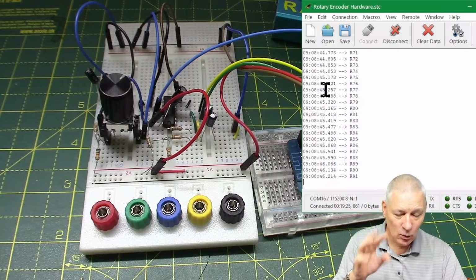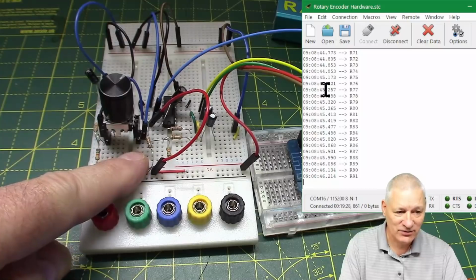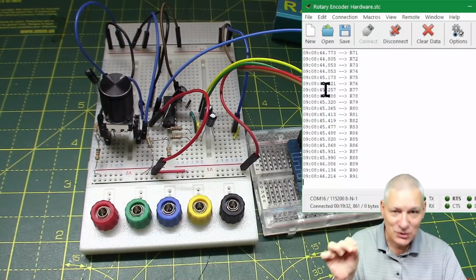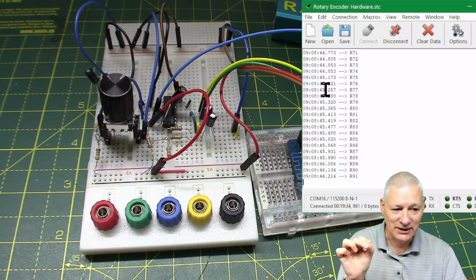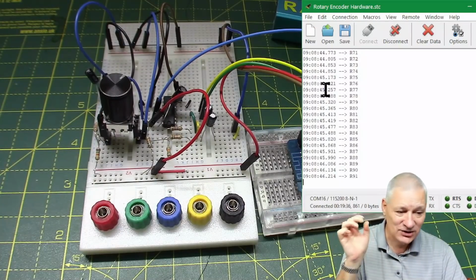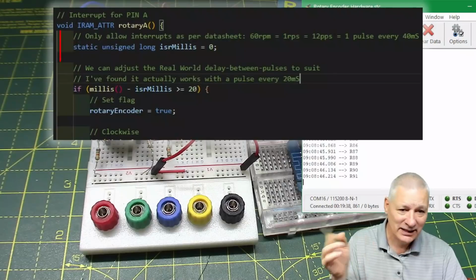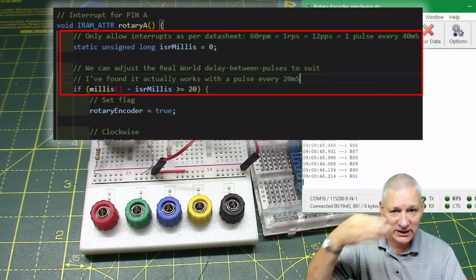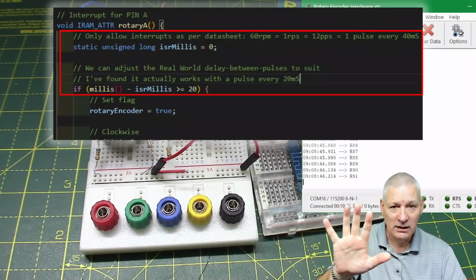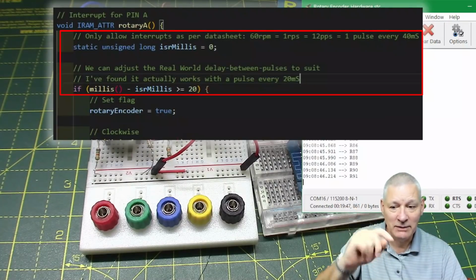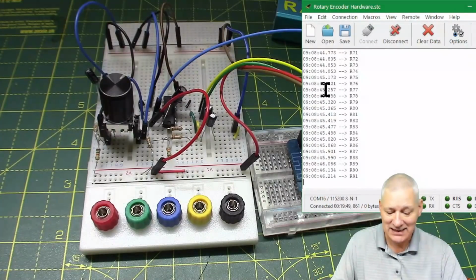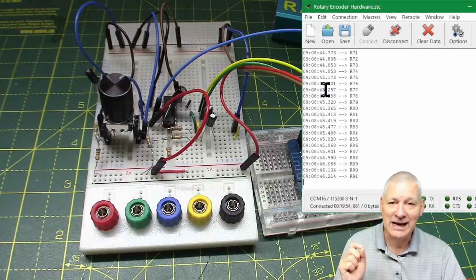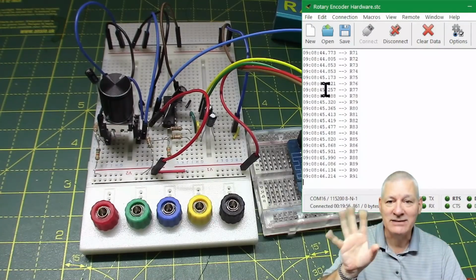So what I've done then is construct this circuit from Jack Gansler, and it absolutely guarantees no switch bounce. So we'll have a look at the circuit. But as well as that, in the software, I've had to say, fine, give me all the interrupts you're going to give me, but if I discover you're sending me pulses too quickly, I'm going to say, no, I'm doing nothing with that. I'm just ignoring it, because that's the manufacturer's specification on here. It cannot guarantee what is being output anymore. Fine, let's have a look at the circuit.